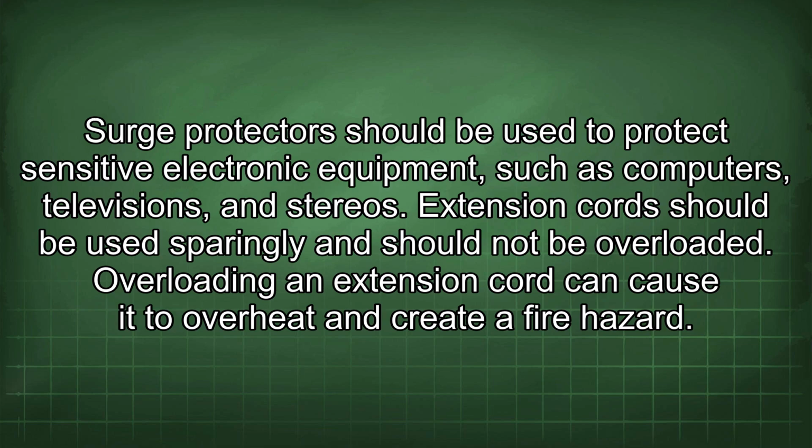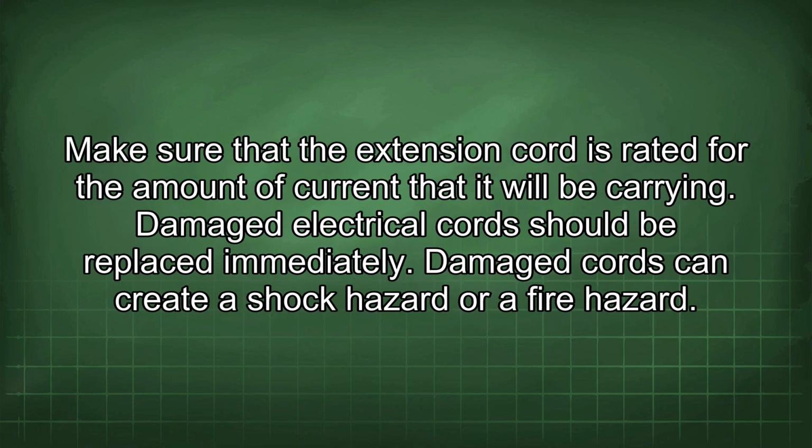Extension cords should be used sparingly and should not be overloaded. Overloading an extension cord can cause it to overheat and create a fire hazard. Make sure that the extension cord is rated for the amount of current that it will be carrying.